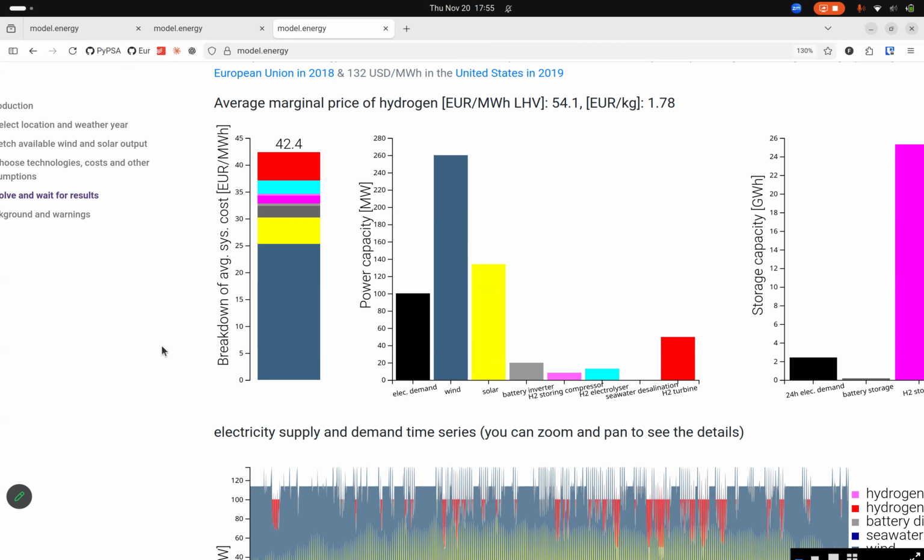You get a nice smoothing effect by aggregating from east to west for solar, because the sun rises in the east, and then you have a later sunset in the far west. If you have a good connection east to west, then you have a smoothed solar feed-in profile throughout the day. It's less spiky. You also average out cloud coverage, things like that.